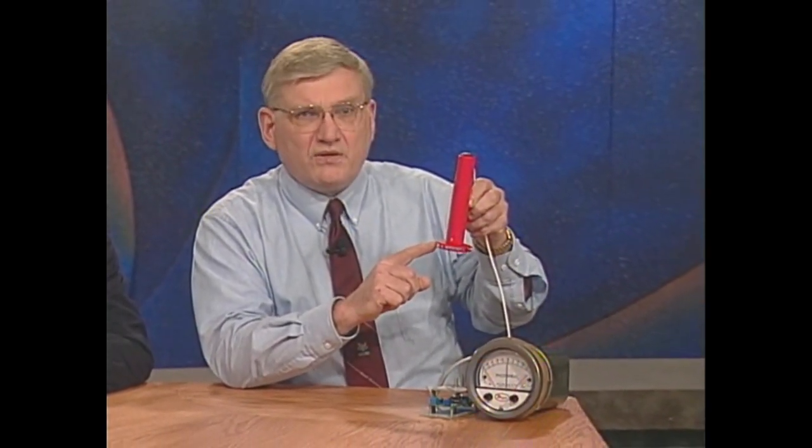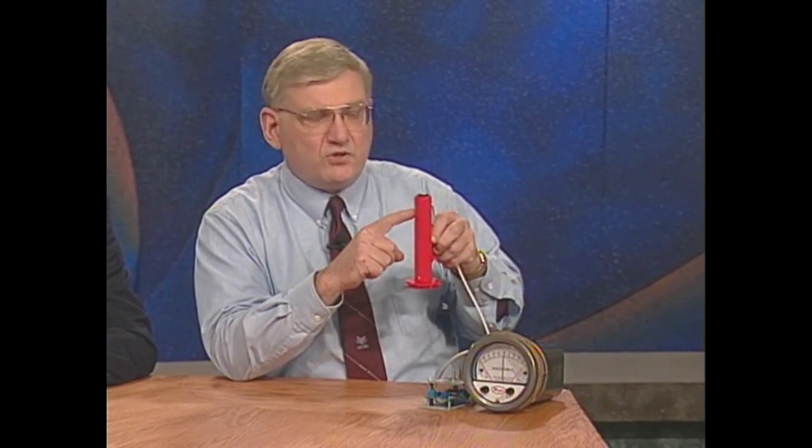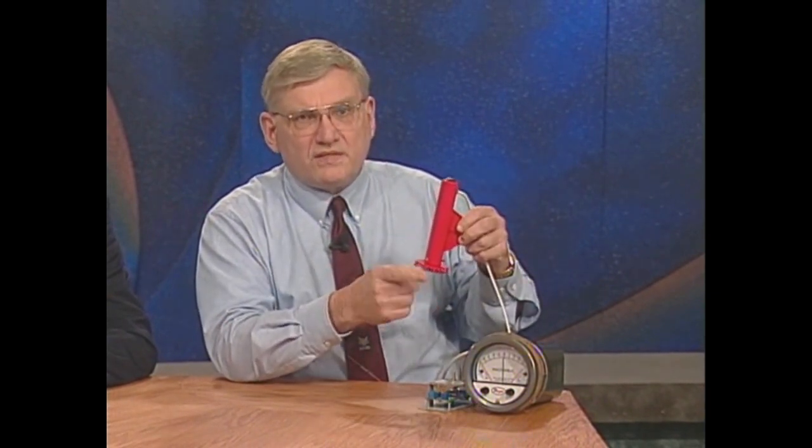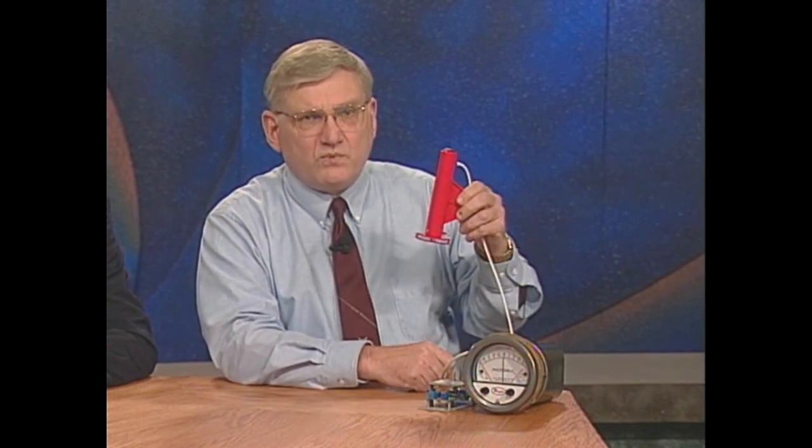Now, accurately sensing the outdoor static pressure is critical to the building pressurization system. It needs to measure an average outdoor static and reject all of the wind gusts. Here's an outdoor air static sensing probe that we've had excellent experience with. It's the Dwyer A306. The outdoor pressure signal is picked up here, sent through this expansion tube, and out through the sensing tube. Watch the meter and see how effectively it rejects the wind gusts.